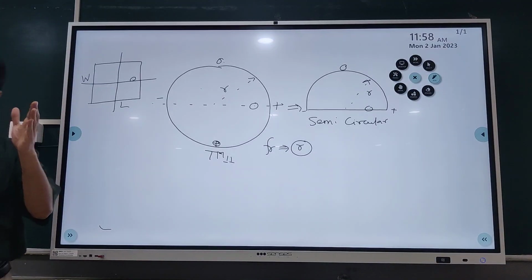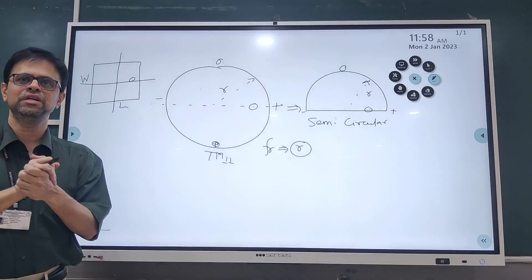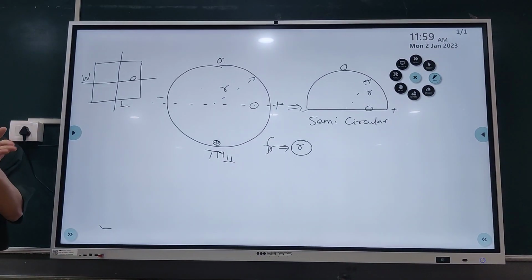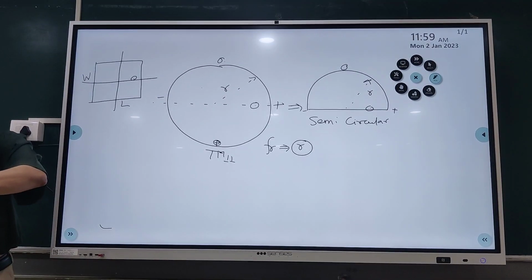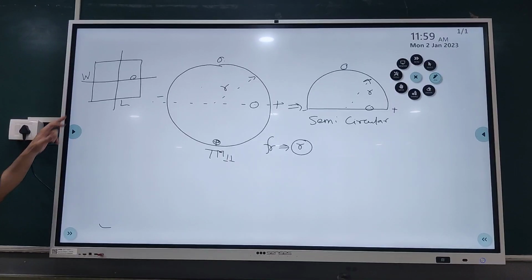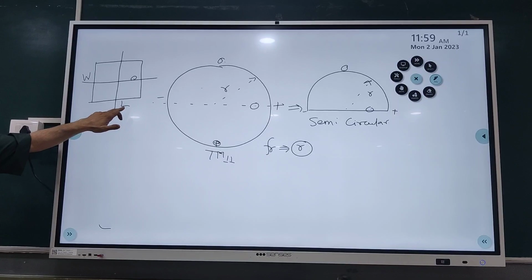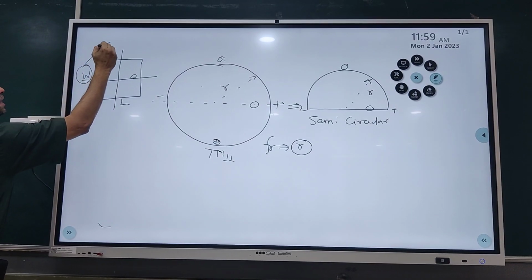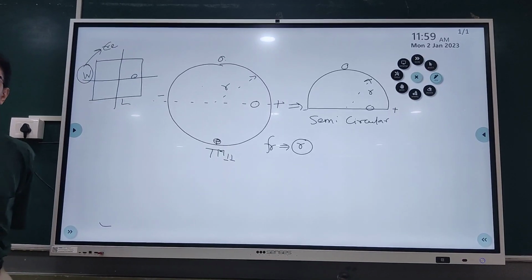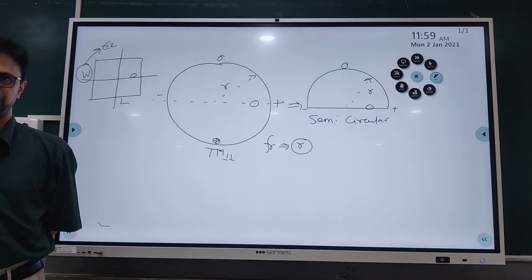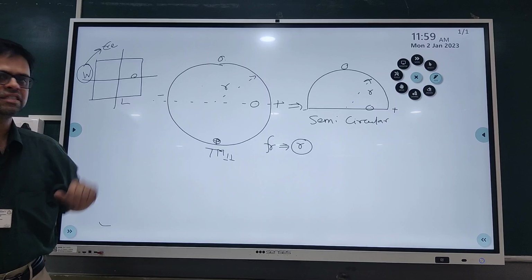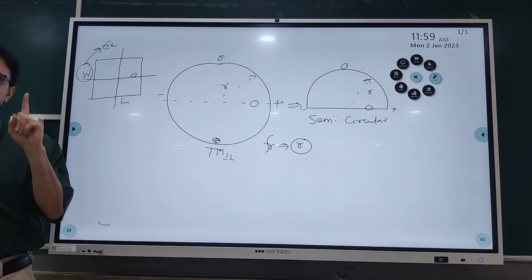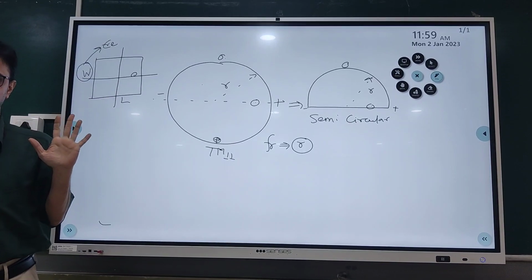Remember, with respect to the calculations of the patch dimensions in the rectangular microstrip antenna design, both the dimensions affect the calculation of the frequency. As we know, when we are calculating the length for the fundamental mode, this parameter has to be considered, as it directly governs the effective dielectric constant of the cavity. Whereas in this case, only the radius r, that is only one dimension of the patch, is governing the frequency.